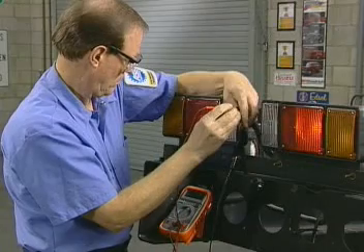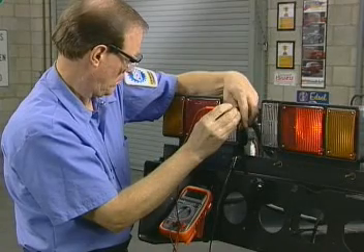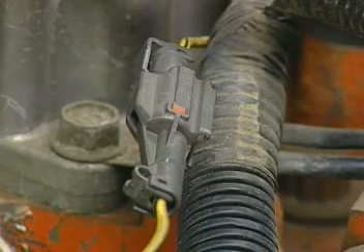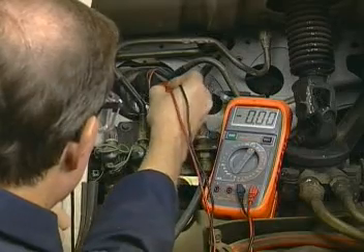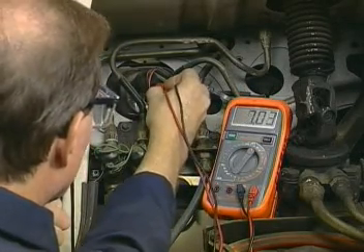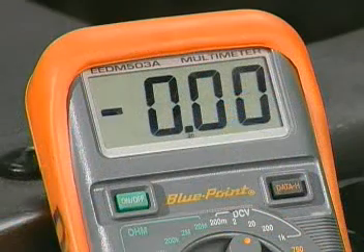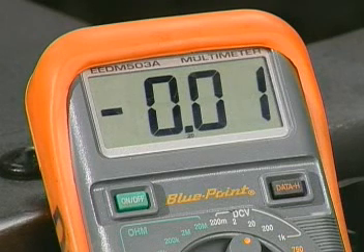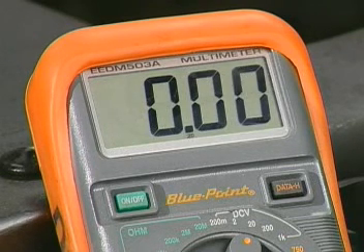The voltage drop across segments of wire will vary by the length of the wire, but should be minimal, as should the voltage drop across switches, relays, and connectors. The loads on a circuit will show the greatest voltage drop as current is consumed in overcoming the resistance of the load. There should be a voltage drop of near 0 volts at the ground, as all voltage will be dropped across the circuit components.